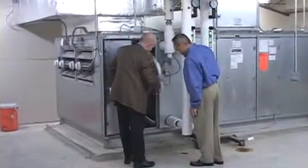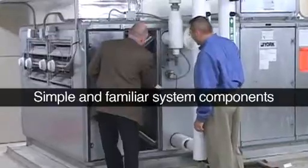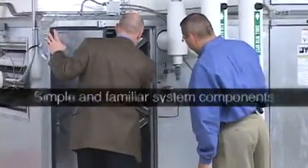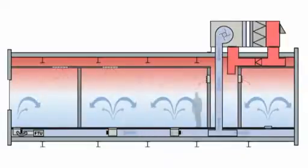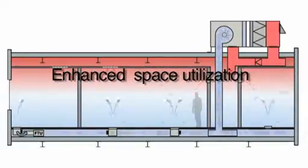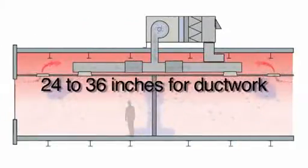Underfloor systems can require fewer filter changes and have fewer moving parts than many overhead VAV systems, and commissioning and balancing these systems is greatly simplified. Underfloor air distribution allows for enhanced space utilization. Often, the interior height can be increased or floor heights can be designed to take advantage of the savings realized by not needing the 24 to 36 inches of overhead ductwork.